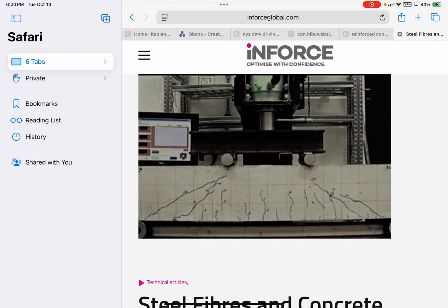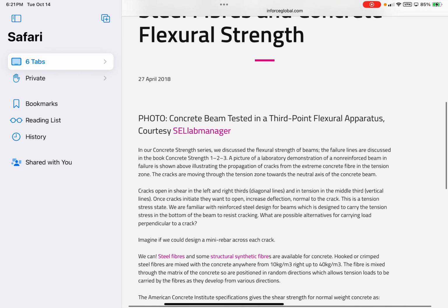For example, towards the middle of a beam subjected to flexure, most of the failure is going to occur at the bottom, because it's just going to split right down the middle because of extreme tension at the bottom. But along the edges of the beam, those are shear failure cracks, which for concrete generally fail at roughly a 45-degree inclined plane. Because of that, you would generally design for the shear and normal stresses along those inclined planes. Does that make sense?